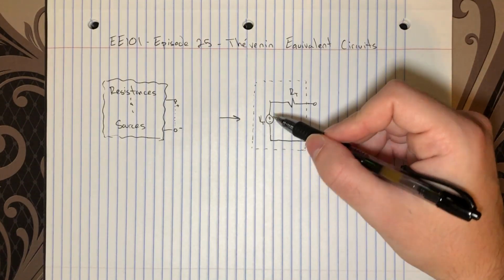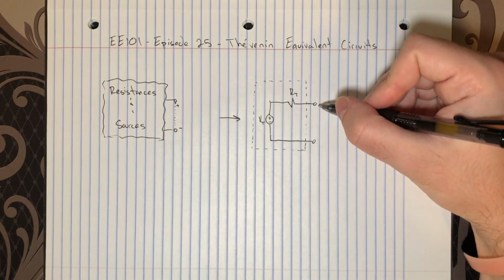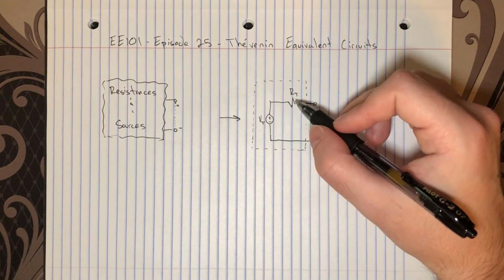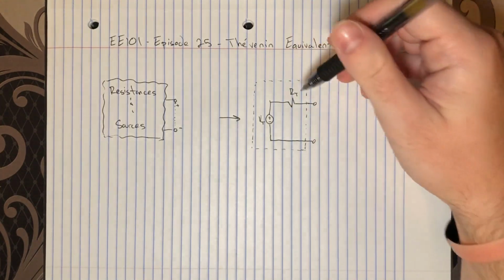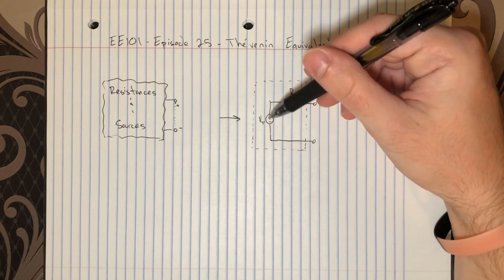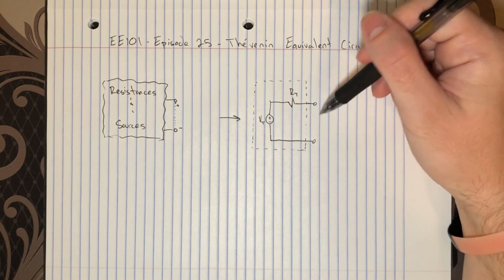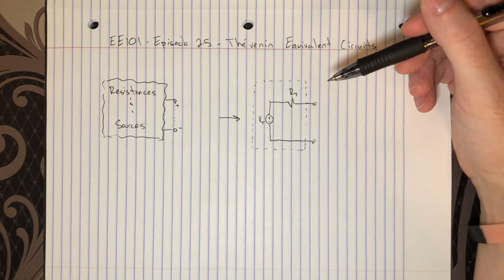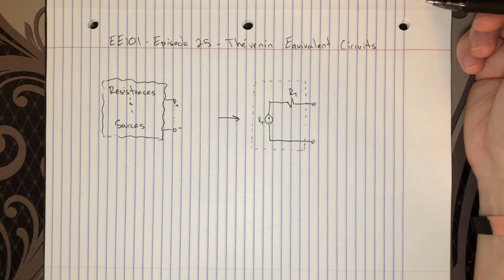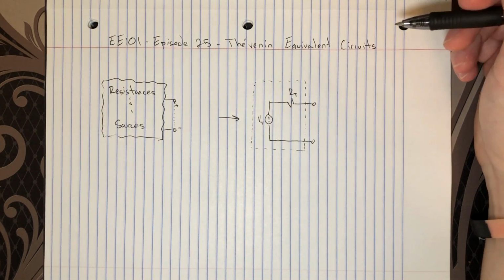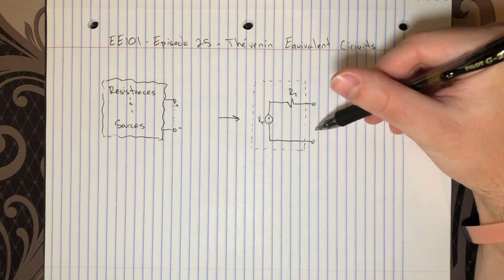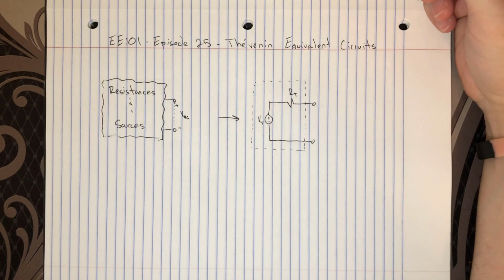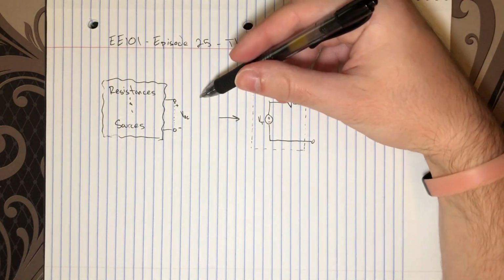This voltage that's generated by this source must also appear across these open terminals, because this resistor is just hanging off here. There's no closed circuit really, so no current can flow, and therefore the voltage VT also appears across these nodes. For that reason, the Thévenin voltage in a Thévenin equivalent circuit is also called the open circuit voltage, because it's the voltage you see across the nodes when they're open like this, denoted VOC for V open circuit. And it's the same thing as V Thévenin.